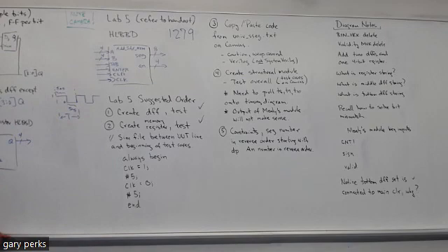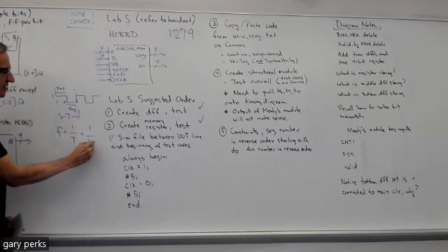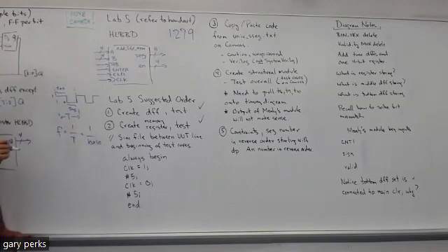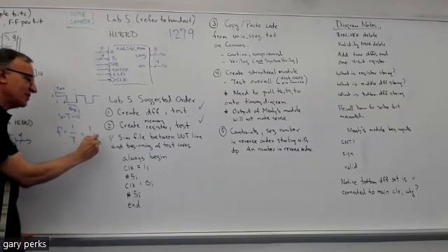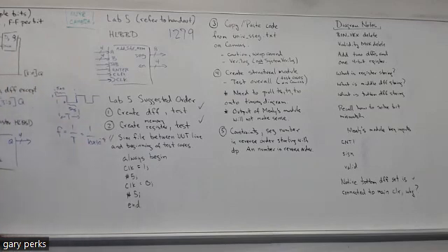How do you get frequency from period? Just reciprocal, right? Frequency is just 1 over period. So the frequency that we're running this clock at is just 1 over 10 nanoseconds. What's nano? 10 to the what? -9, right? Not -6. People always confuse nano and micro. Micro is -6, nano is -9. Does anyone know what 1 over 10 times 10 to the -9 is? What frequency that is?